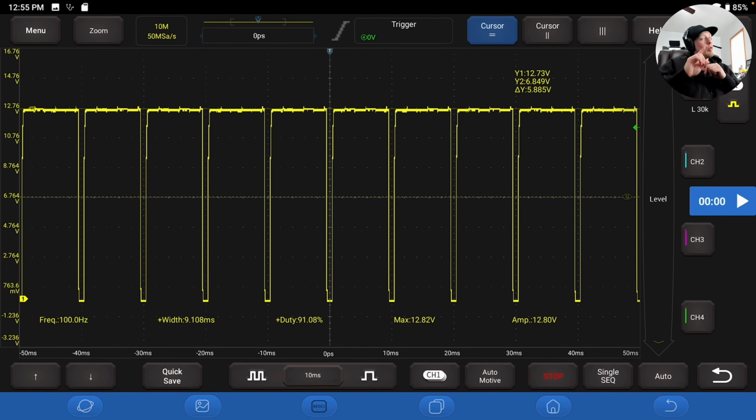But again, if we weren't sure about this, we can go look at it with the scope. Obviously, this is an intentional mechanism that's designed into the circuit by the manufacturer. But if we're still not sure, we could go back over to the passenger side where we had no fault codes and a perfectly functioning bulb, and we could back probe the positive wire at that side of the vehicle, and we would see the same pattern, and we could also make the same voltage drop measurement that we did on the driver's side, and we would measure something in the exact same general range, right?